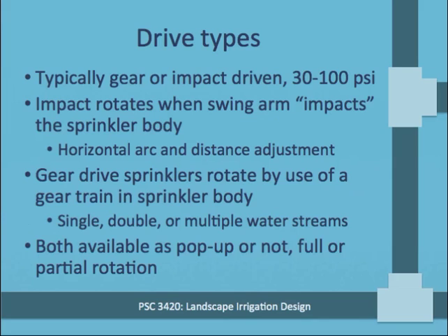Now with those rotary heads, they've got different drive types. They are typically gear driven or impact driven with pressure requirements of 30 to 100 psi. Impact-driven heads rotate when a swing arm impacts the sprinkler body. And they've got some different adjustments, including horizontal arc and distance adjustment.